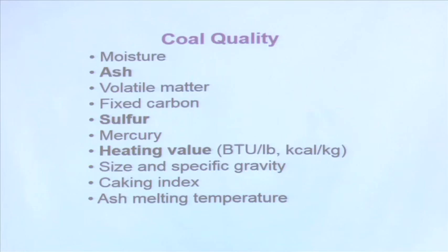From outside it is very difficult to know how much water is there, and that water we cannot do anything about. That is called the inherent moisture, and that goes out at around 560 degree centigrade temperature, that is called dehydroxylation temperature.